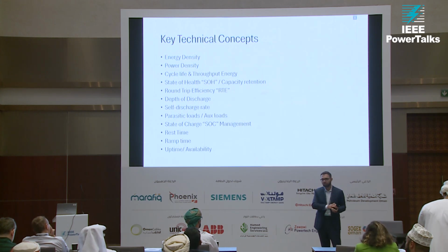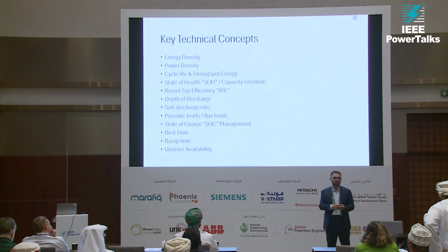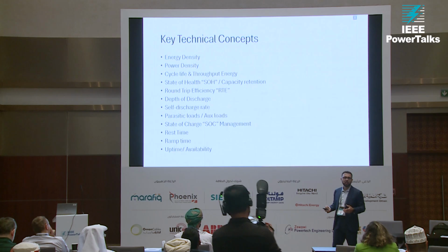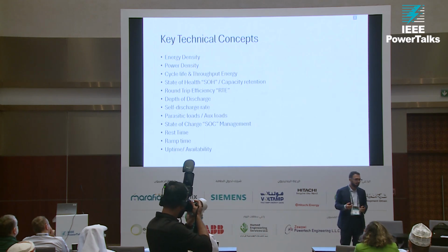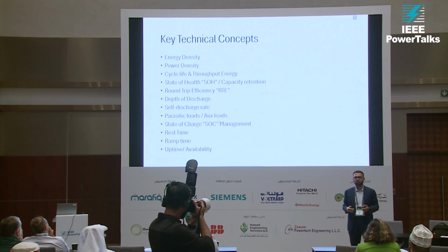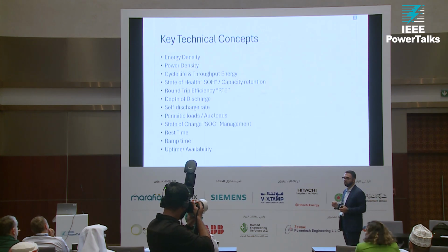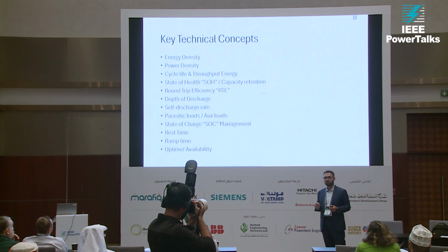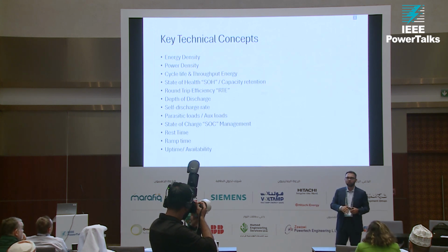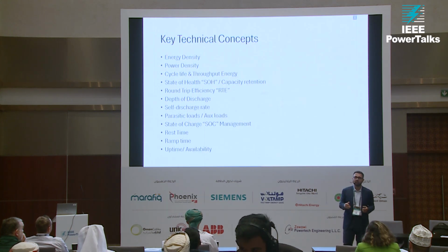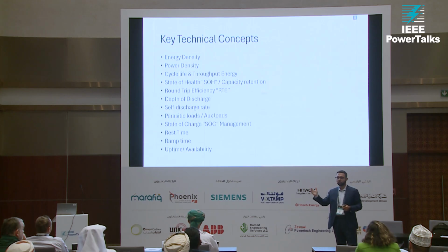So that's the measure. What are your full losses across a full charge to discharge cycle? Different technologies have different losses. Electrochemical technologies like lithium-ion are doing impressively well. On a DC level, you can get batteries that are up to 95% efficient. On a complete level, up to the POI, including your inverters and transformers, you can get up to 90%. So if you're charging 10 megawatts, you're discharging 9, which is pretty impressive compared to other technologies.